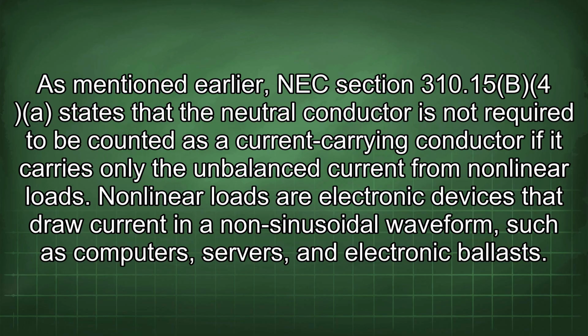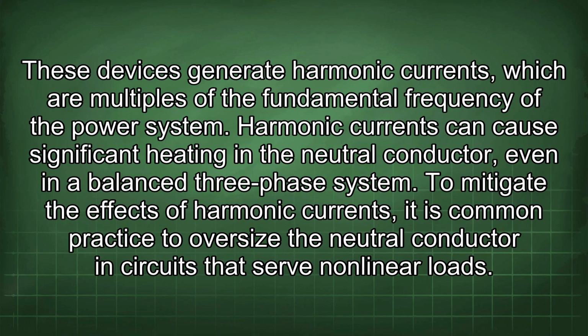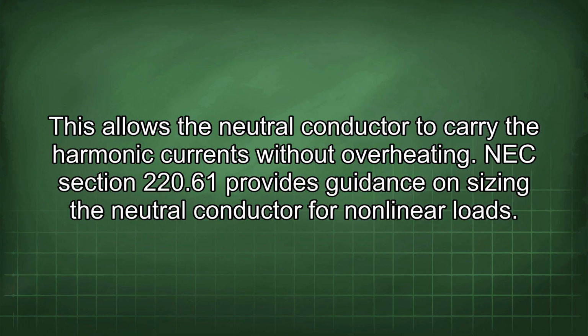Nonlinear loads are electronic devices that draw current in a non-sinusoidal waveform, such as computers, servers, and electronic ballasts. These devices generate harmonic currents, which are multiples of the fundamental frequency of the power system. Harmonic currents can cause significant heating in the neutral conductor, even in a balanced three-phase system. To mitigate the effects of harmonic currents, it is common practice to oversize the neutral conductor in circuits that serve nonlinear loads. This allows the neutral conductor to carry the harmonic currents without overheating.